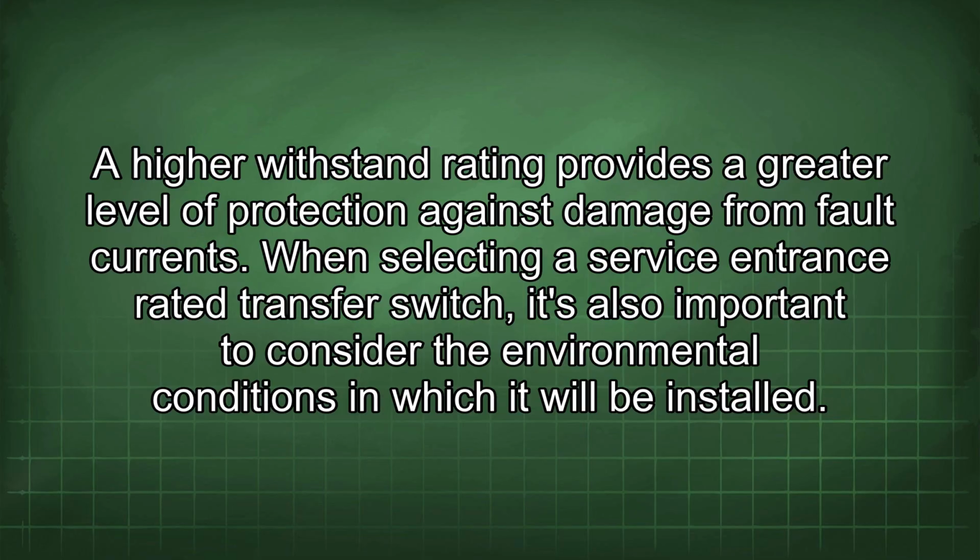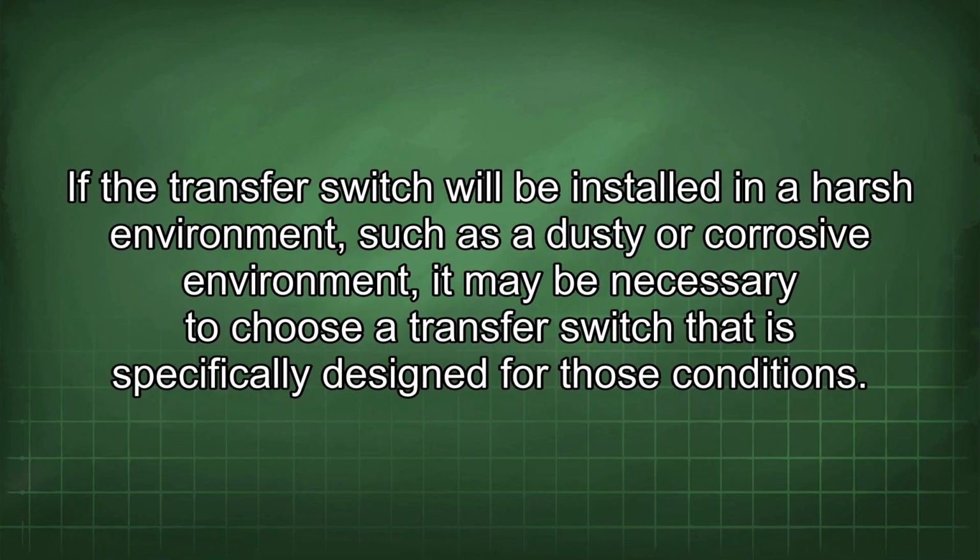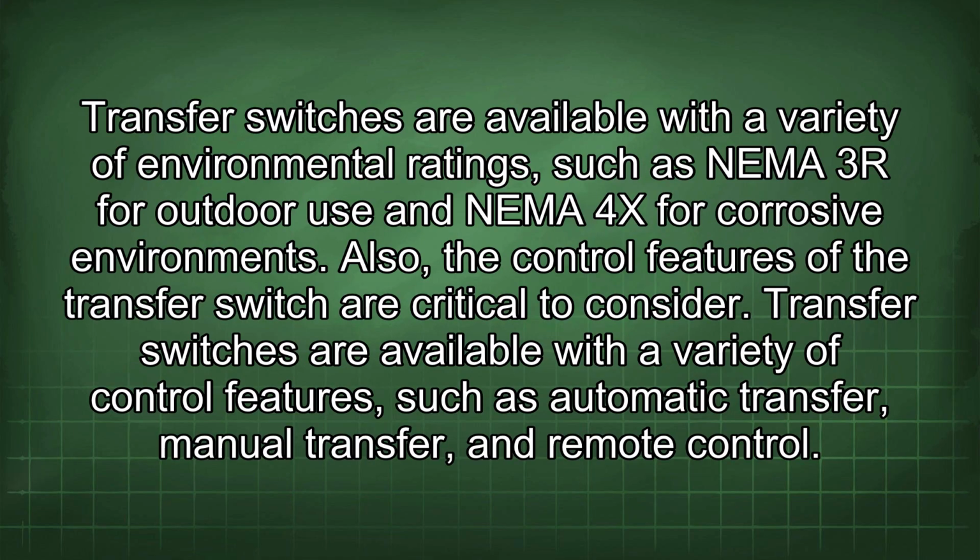When selecting a service entrance rated transfer switch, it's also important to consider the environmental conditions in which it will be installed. If the transfer switch will be installed in a harsh environment, such as a dusty or corrosive environment, it may be necessary to choose a transfer switch that is specifically designed for those conditions. Transfer switches are available with a variety of environmental ratings, such as NEMA 3R for outdoor use and NEMA 4X for corrosive environments. Also, the control features of the transfer switch are critical to consider.